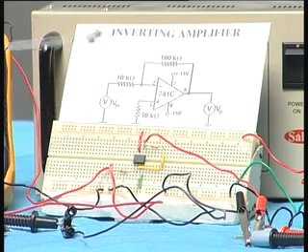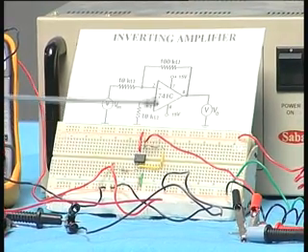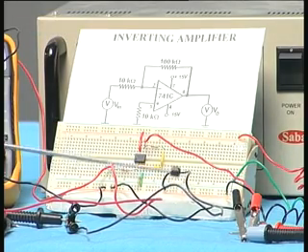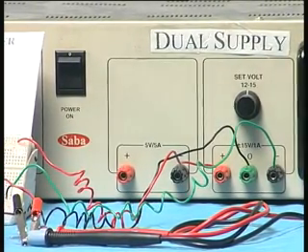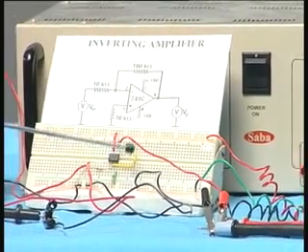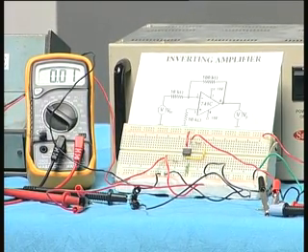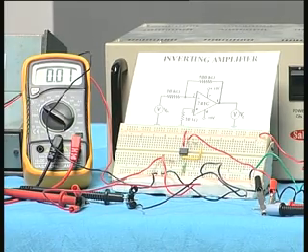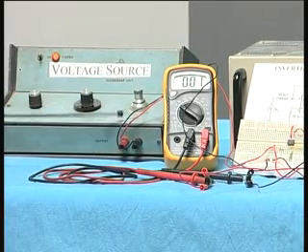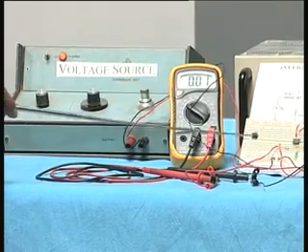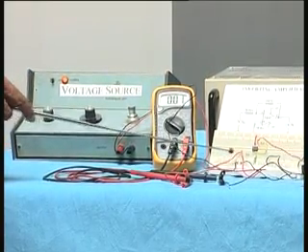Now this is the output voltmeter. Here this is the op amp, you can see the 7 is connected to the rail voltage, which is connected to plus 15, and the bottom black is the ground and the green is the minus 15 volts, and you have the two resistors, the 10k and the 100k, connected in the feedback, and there is a 10k resistor which is coming from the pin number 3. So this is a voltmeter, it is measuring volts, and this is a voltage source which you have seen in the earlier experiment. So I can change the dials and change from millivolts to volts, and that is connected to the input of the amplifier, between the terminal 2 of the resistor and the ground.